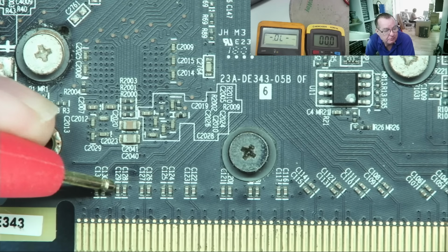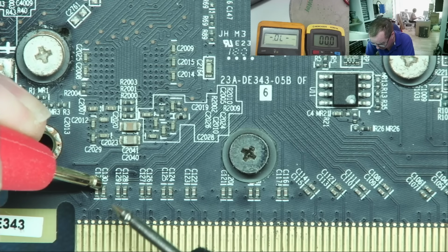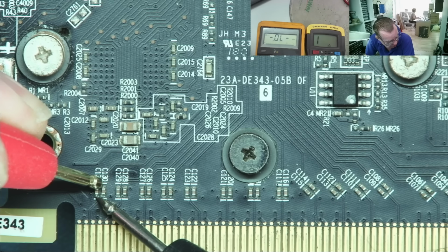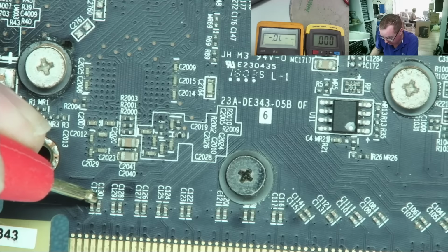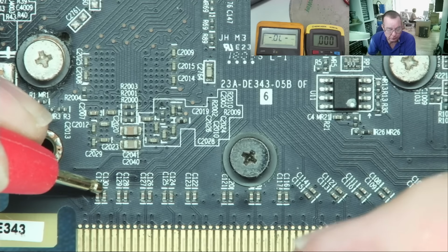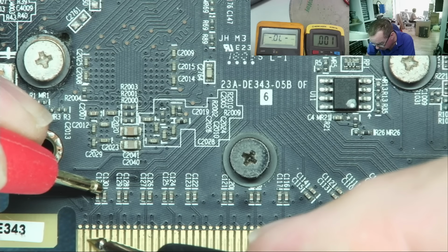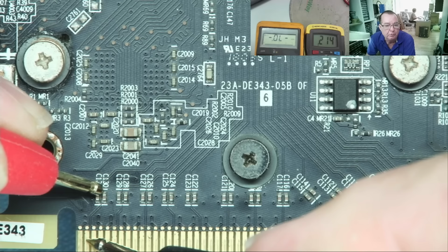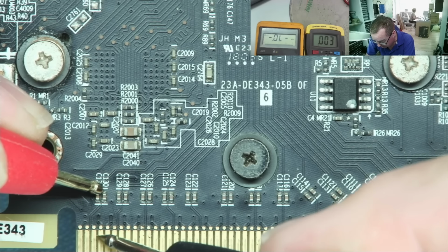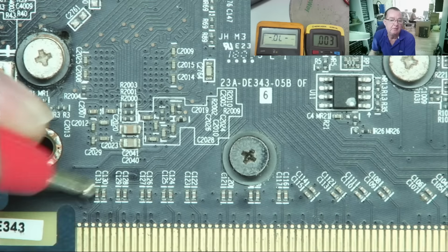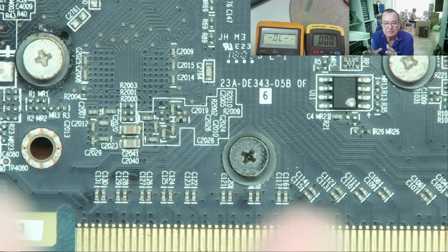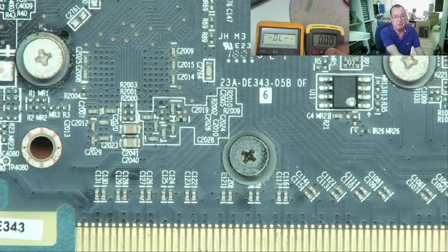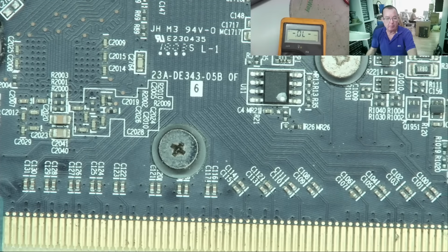Let's have a look. This is not a very good meter probe. I can get on it. Okay, they're more than 200 nanofarads. Let's have a look. It's just as easy just to go to the place it's going to. Yeah, 200, yeah, 240. So these are 220 nanofarads basically. They're not always the same on all cards, so don't just think they're always 220. I have seen some that were about 100 on other cards. So back to what we were doing.